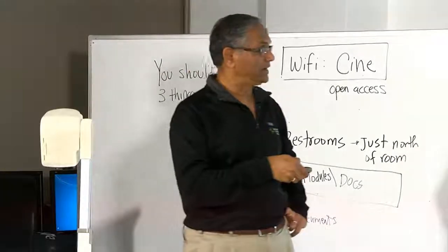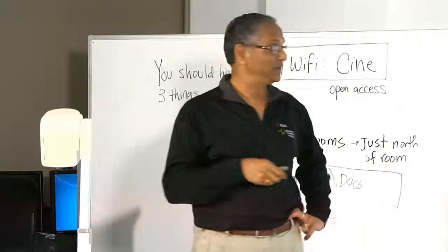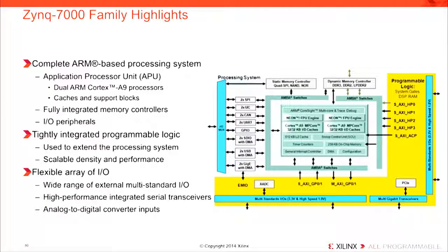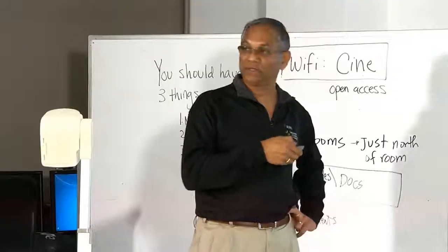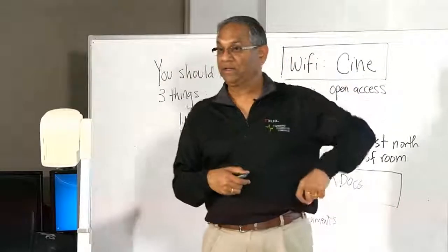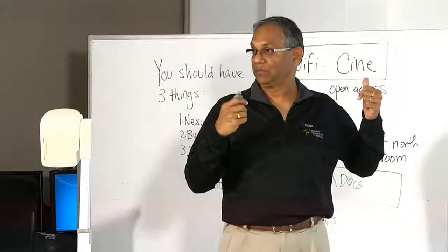It also has 512 kilobytes of unified level 2 cache. It also has a Snoop controller, triple timer counter, interrupt controller, DMA engine, and so on. Besides that, it has a bunch of peripherals, okay, like CAN controller, the SPI controller, I2C, and so on, and USB controller. So you can connect an Ethernet port to this port, and it can start working.